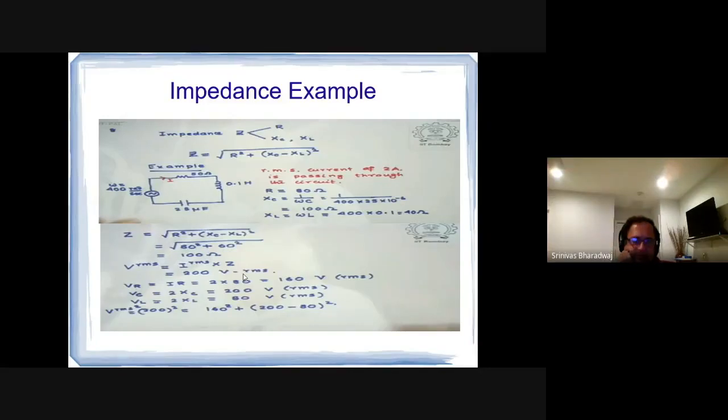Okay. So now impedance consists of the R, then the XC and XL. So you have the Z. Now Vrms equals Irms times Z. V equals IR, as I explained to you. Z is impedance and is measured also in ohms. Remember the XC? We write it as 1 over i omega C, and XL equals i omega L.